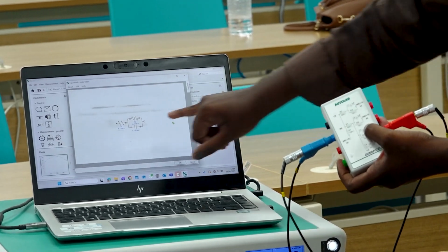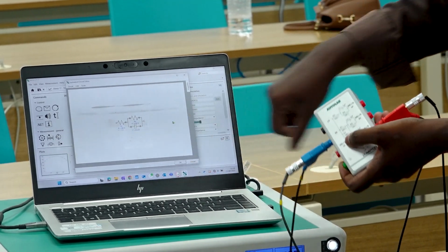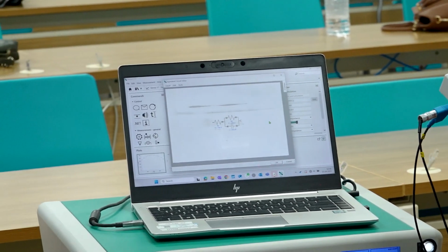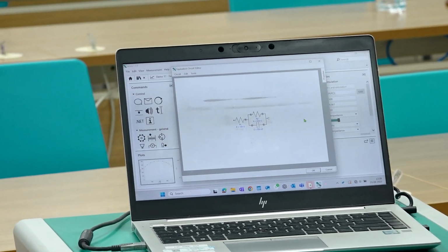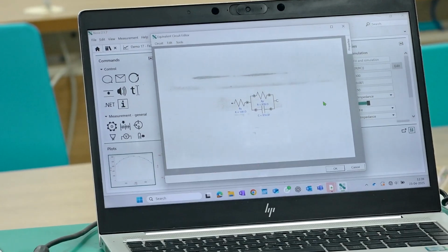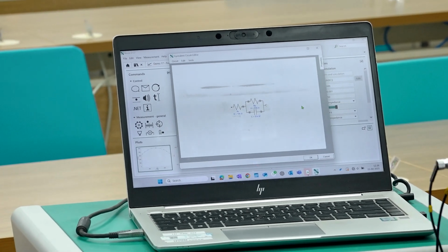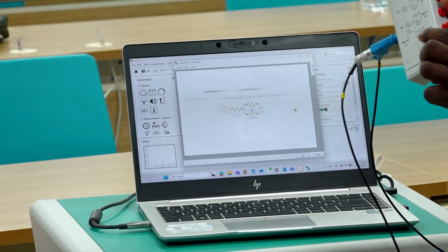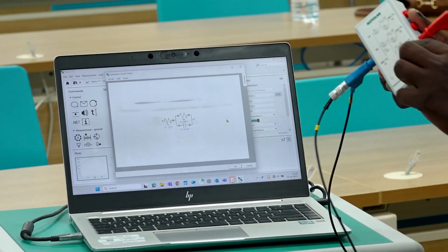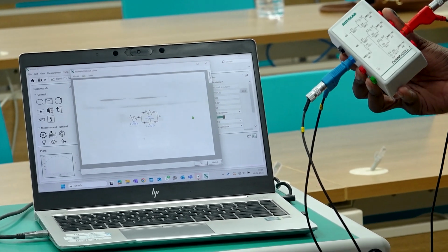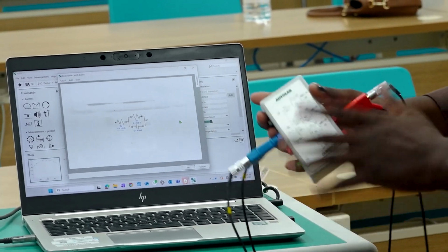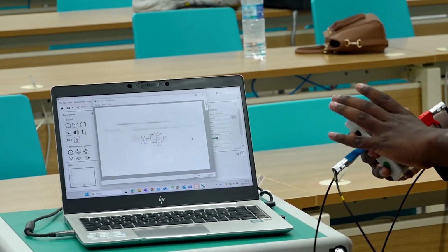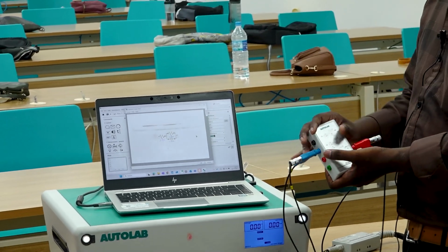Another one is the capacitance, which is 974. What is that, nanofarad or microfarad? Nanofarad. So 974 nanofarad. Here it is mentioned as 1 microfarad, meaning out of 1000 nano we get 974 nano, because these are old dummy cells brought just for demo purposes, so some slight variations will come.